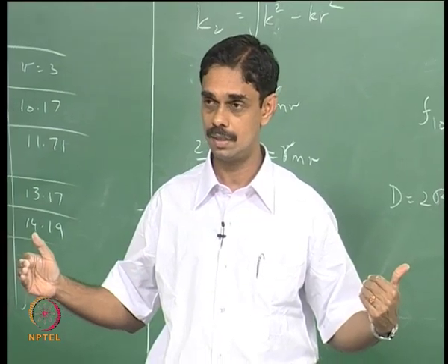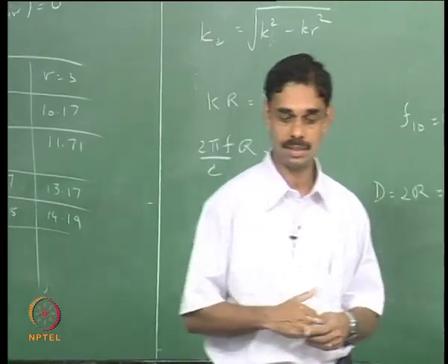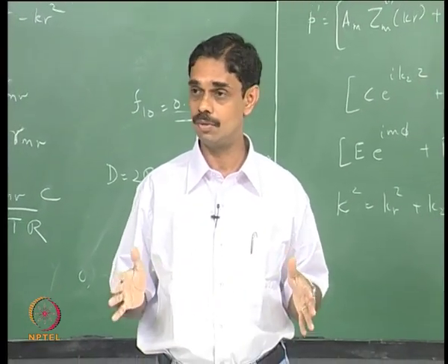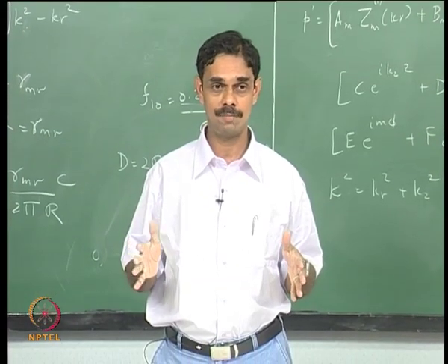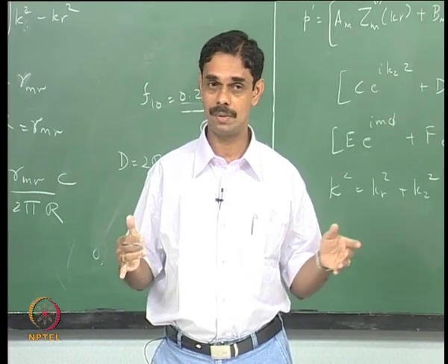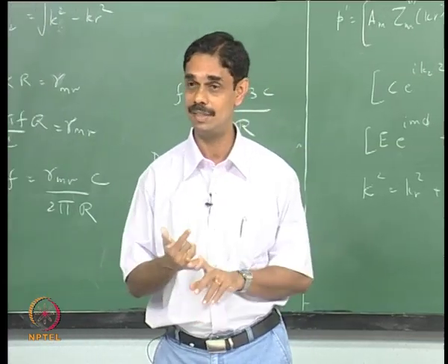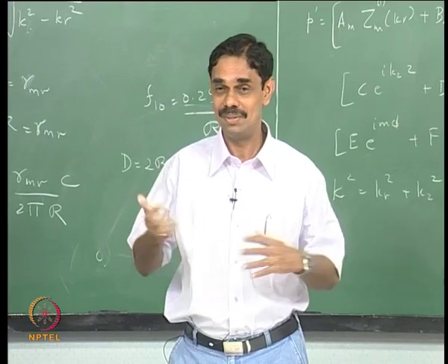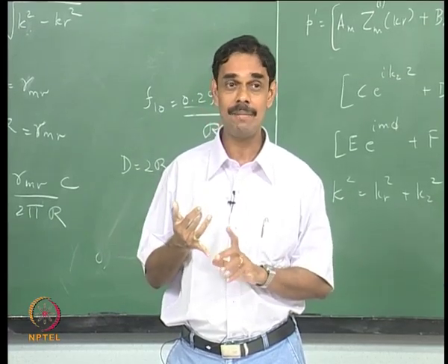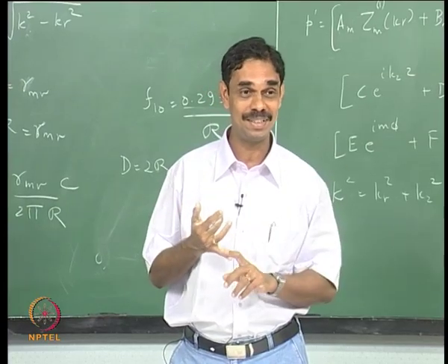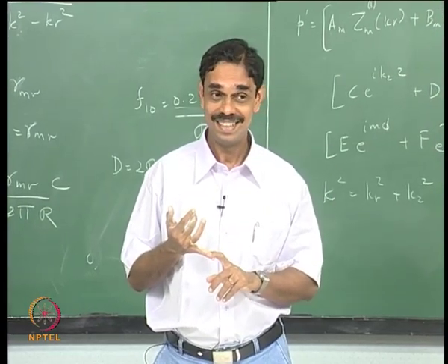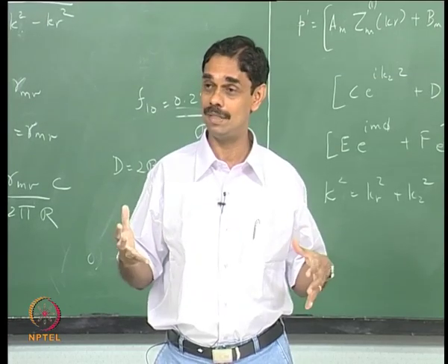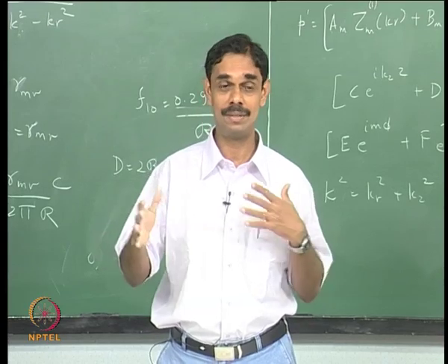So I will stop here with my teaching on acoustics, and in the next class we will start the second half. We have finished the first half of the course, which I said was dealing with propagation of sound. Just to recap what went through half the semester: we derived the equations of fluid mechanics, one dimensional, and then you can write 3D if you want. The important thing was that the continuity equation is not rho A V equal to constant, but dou rho by dou t plus del dot rho v equal to 0, and it is really important that we keep the d by dt terms in continuity, energy and momentum.